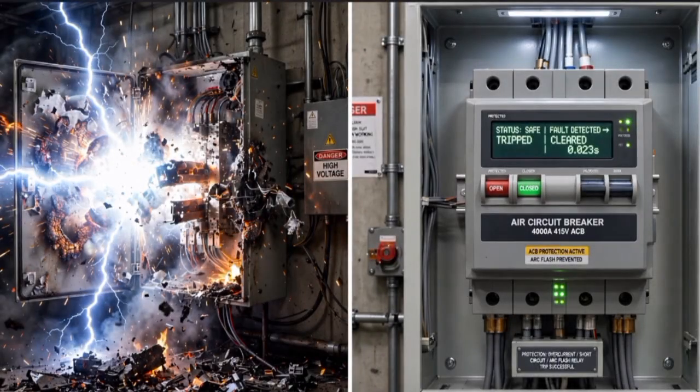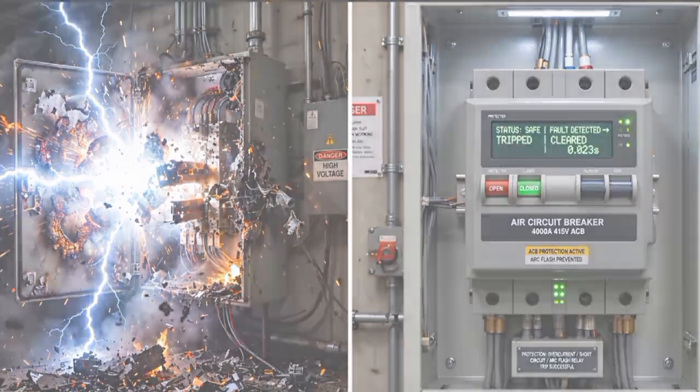Arc flash. An arc flash is like a sudden explosion of heat and light from an electrical arc. This flash can cause severe burns and even injuries that last forever or death if someone is nearby. Arc flashes are especially dangerous in places like factories, where there are large electrical machines. Preventing catastrophic damage relies on heavy-duty protection, such as air circuit breakers (ACB), which are designed to handle high currents and trip instantly to minimize arc energy.